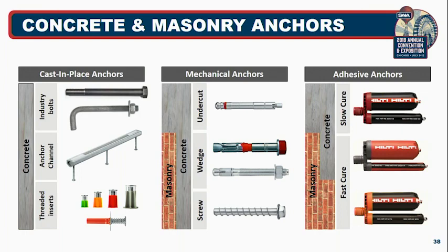However, we're seeing screw anchors taking a bigger chunk of the market from wedge anchors. They seem to be popular with contractors because there are certain things that they offer that the standard wedge anchors don't. Once you've installed the wedge anchor, that's set. If you need to get rid of them or pull them out, basically you've got to cut them off or burn them. It's very difficult to remove once those anchors have been set.